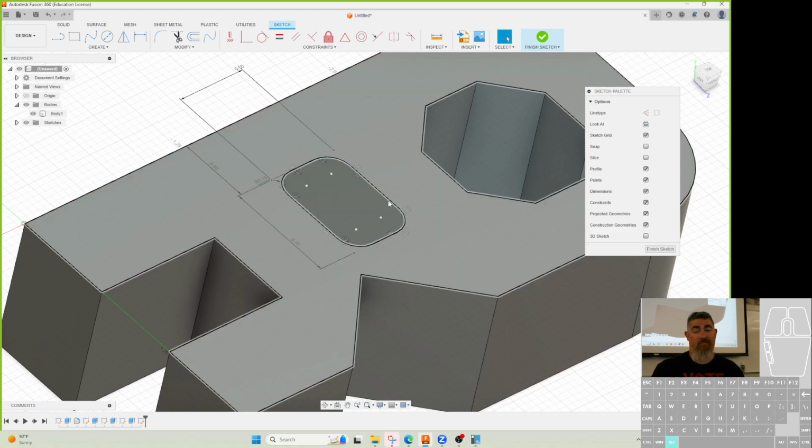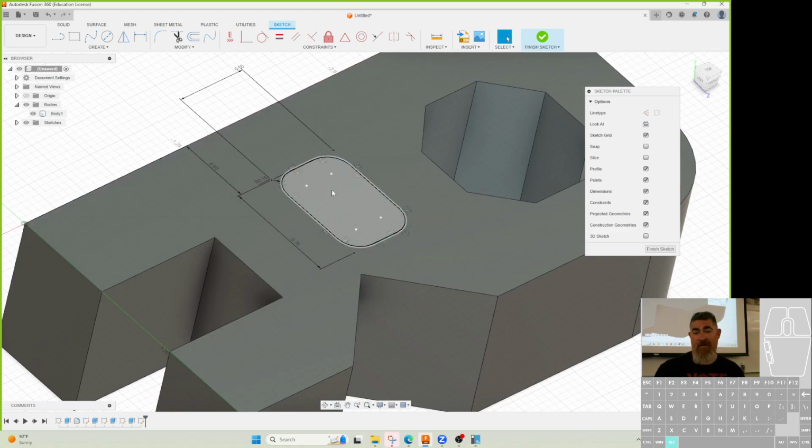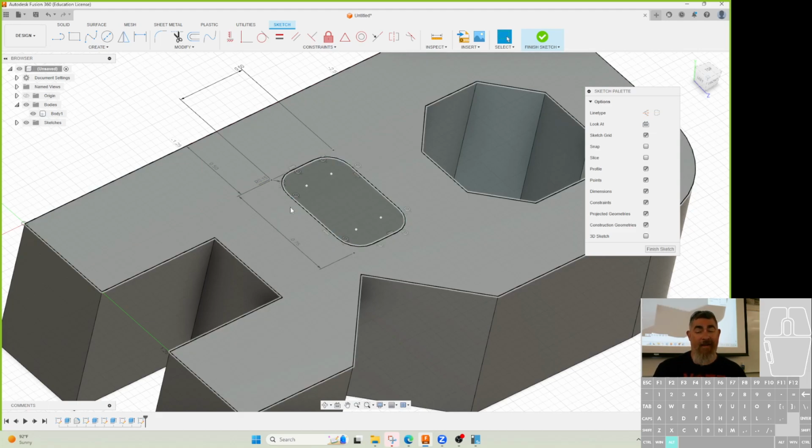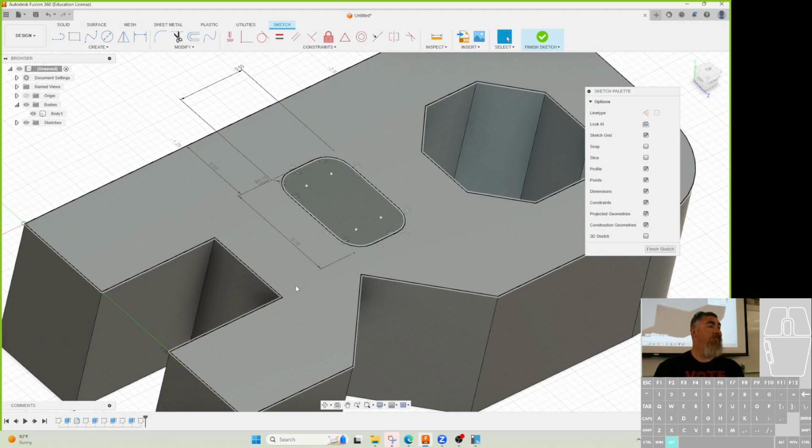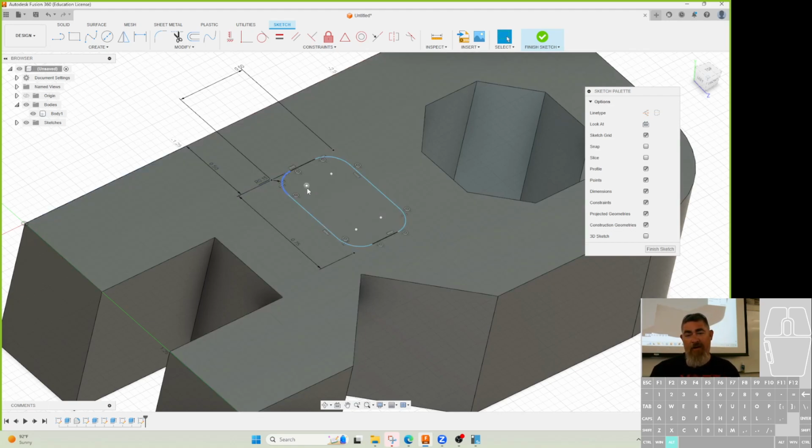But also, now if I want to take the sketch, if I decide, oh, I don't want those fillets, what do I have to do? I have to delete each one, make it sharp again in the sketch. That's a lot harder than just turning off a feature, right? So that's why the feature is easier. But if I needed to know center to center distance, then yeah, maybe it's important.